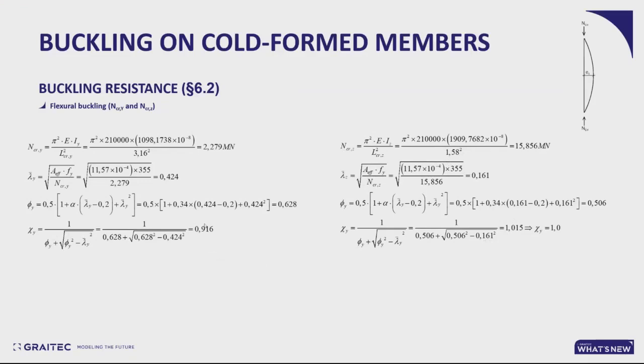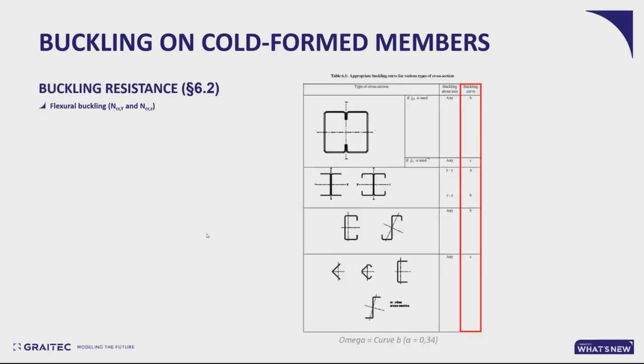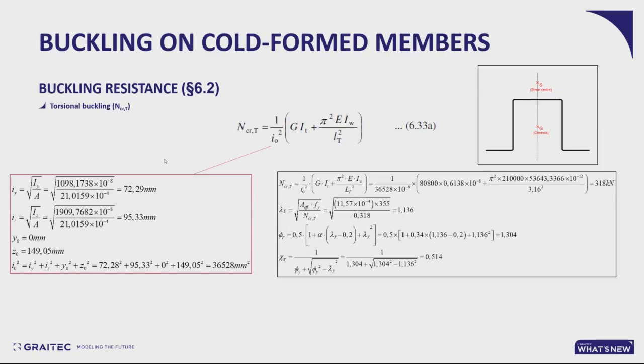And as you can see, the flexural buckling was not much of an issue there, because at worst you've got a 10% reduction on the resistance. But then you've got the torsional buckling effects, which depend on the torsional and warping resistance, which are very low there, and also this I-O parameter depending on the distance between the center of gravity of the section and its shear center, which is very far away, giving you a significant value for I-O and lowering the critical force for torsional buckling.